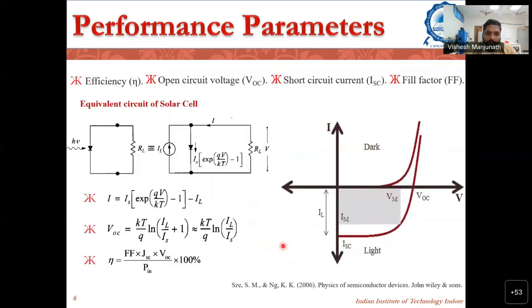So when we talk about solar cells, we have to analyze what is efficient and what is not, and what parameters we have to look into, even if you buy a solar cell. It works on a simple diode model. You give some light and connect it across a load. When you solve all the KCLs and KVLs and the equations at particular nodes, you get the IV graph. Out of this IV graph, you can find out the efficiency.